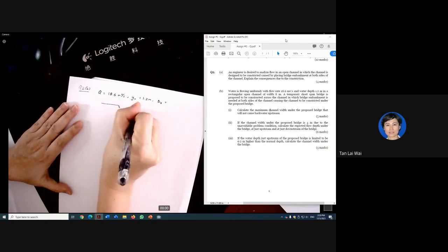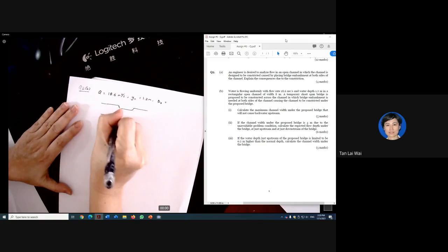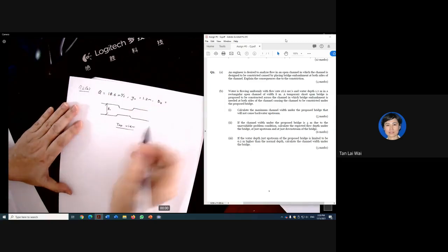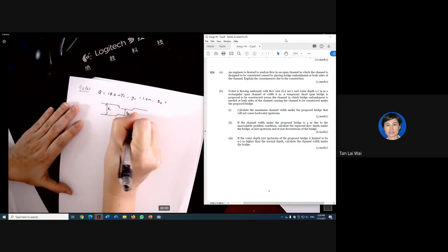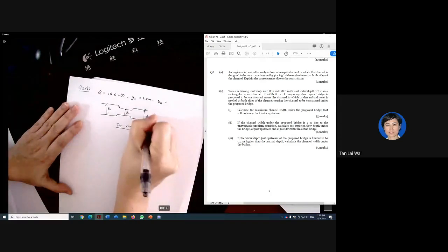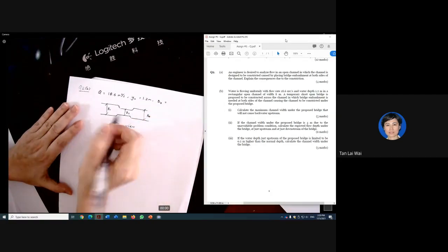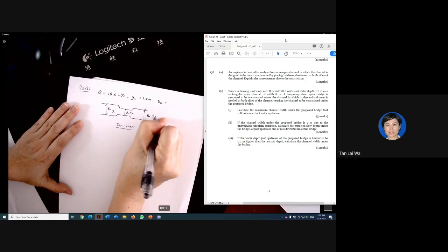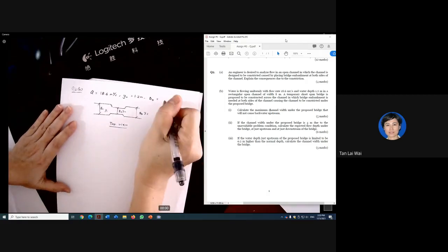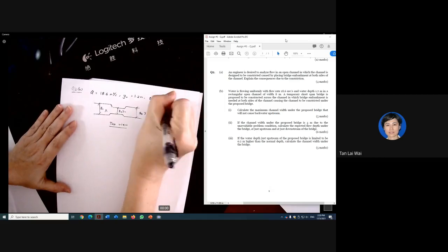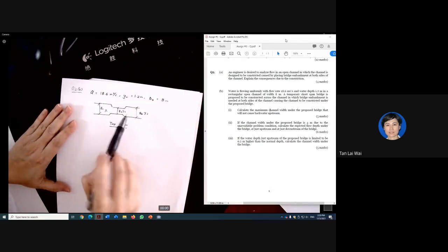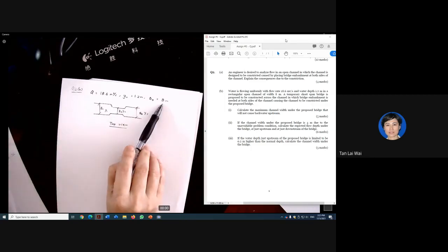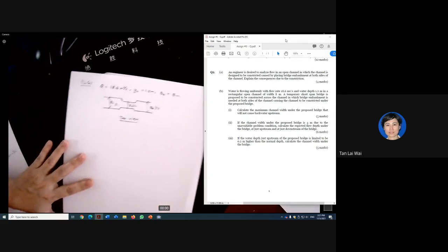So at location 2, the channel is going to be constricted. I have here B0, and I have here B2. Again, this is B0. This is the location where we are going to have our Y1 here, Y2 here, and also Y3 here. The question gives B0 as 8 meter. That means whenever it is constricted, B2 will be less than 8 meter.